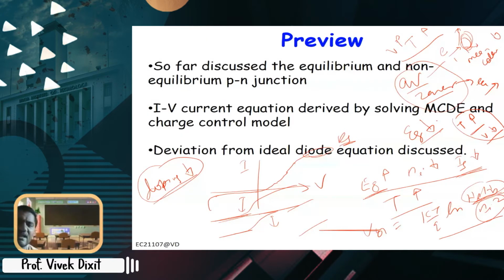Okay, and you can also think like this. As temperature increases, it is easier for the electron to move away from the bonding. They are relatively more free, and the crystal has more vibrations. If the breakdown voltage is increasing with temperature, it is avalanche.